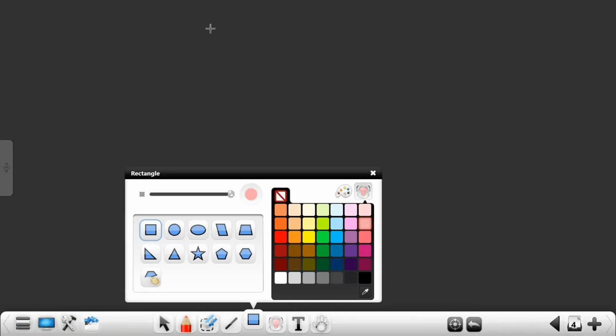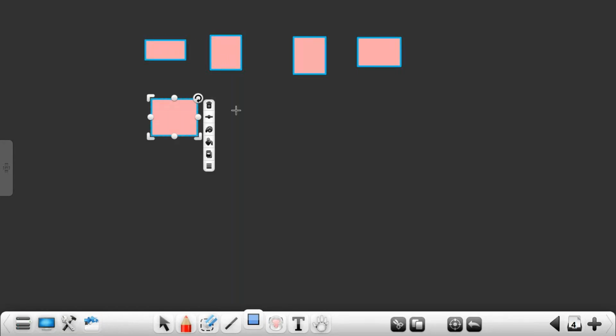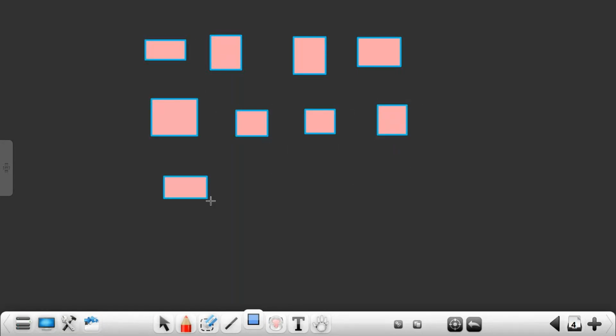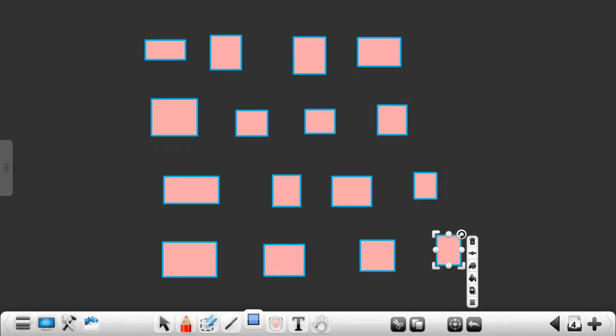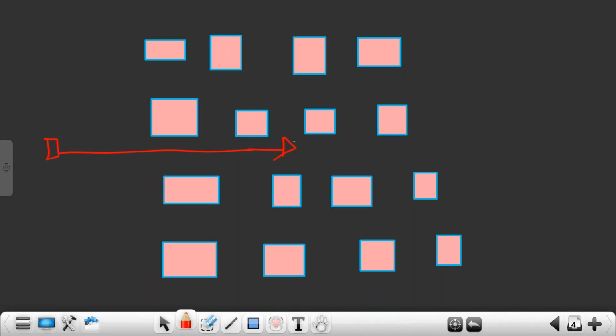So when you have flip-flops like this, right? Now what you will do, you will build a tree. How do you build a tree? You have a port. From the port, use one buffer. From this, use one buffer here.